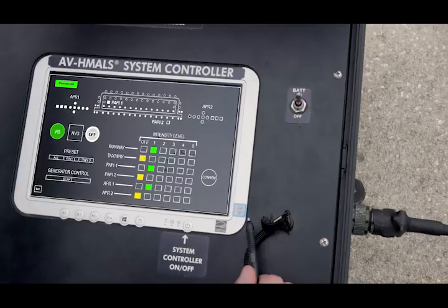To control the lights, first select your mode, either visible or night vision. Next, select a light group, such as the runway or a specific PAPI system, and set the desired intensity level. Finally, press the Confirm button. The indicator light for that group will turn from yellow to green, confirming the command has been sent.